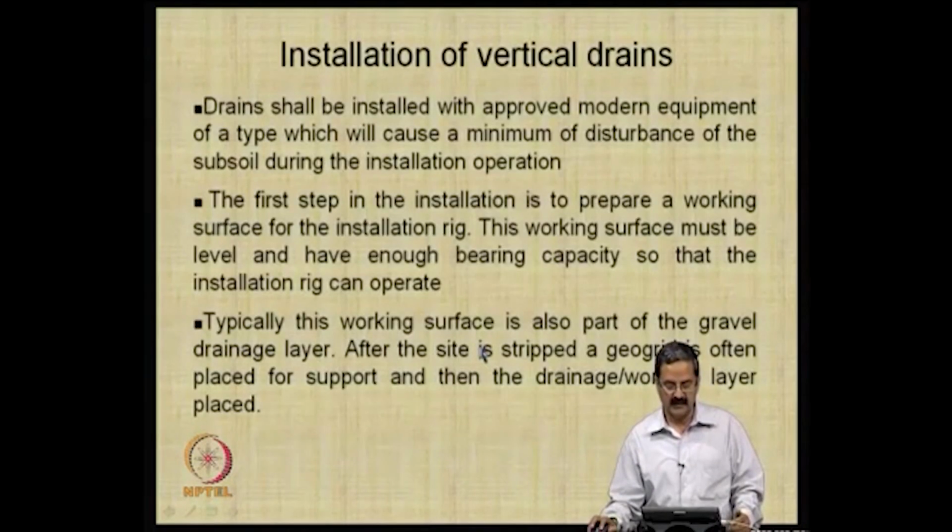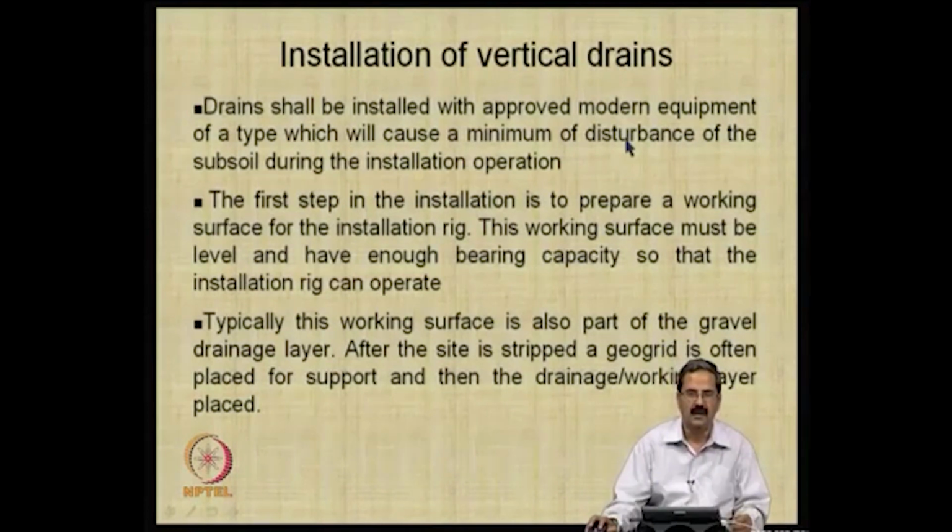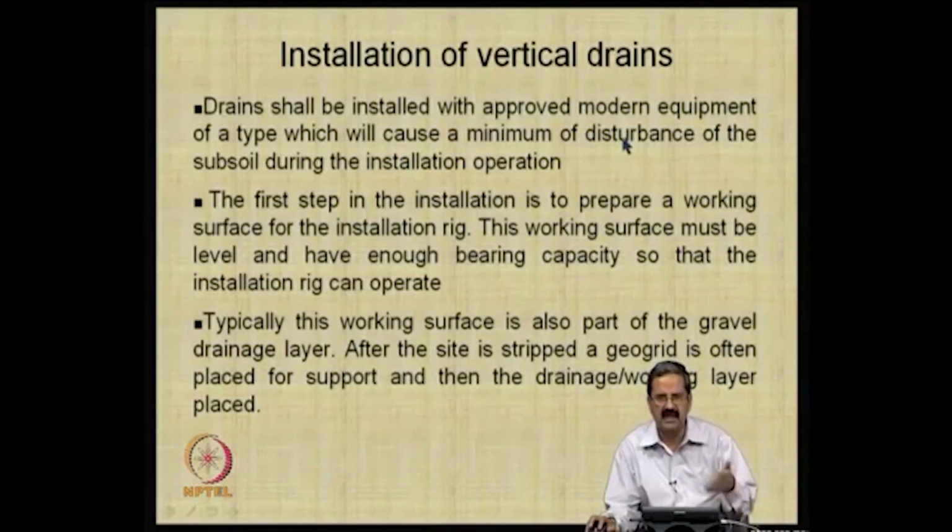So, as I just mentioned, we will see how it can be installed, like of course, you saw the video, and we should have very good modern equipment. In fact, some companies must have good approved equipment which causes minimum disturbance of the subsoil during installation, because disturbance leads to reduction in permeability, that is again an issue.